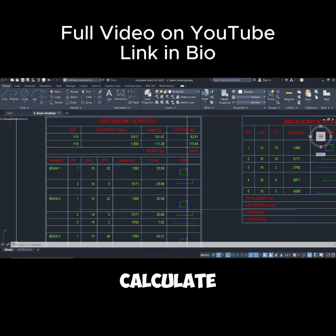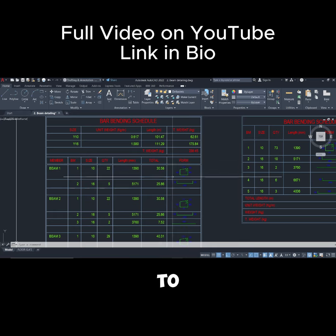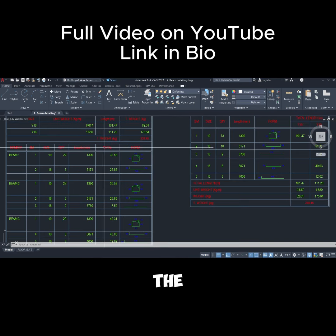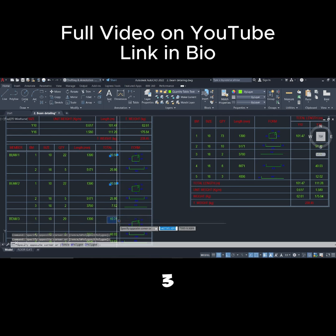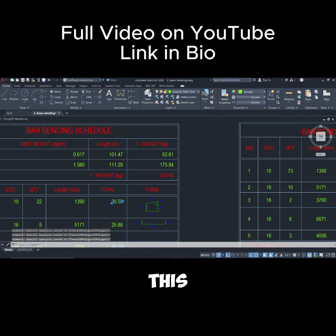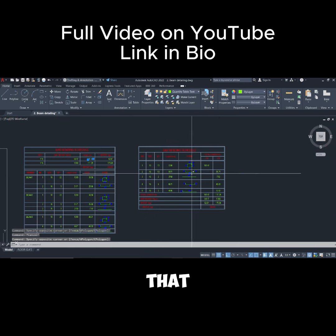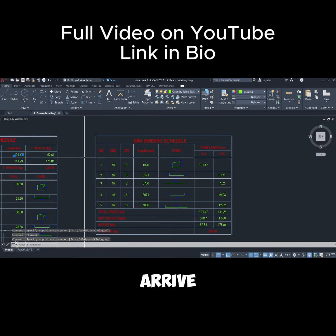But we need to also calculate the total number so that the QS can just come to your bar bending schedule and read the total number of 10 mm reinforcement, total number of 16 mm reinforcement. To calculate the total number of 10 mm, we need to add up 10 mm in beam 1, 10 mm in beam 2, 10 mm in beam 3. So addition of all of this will give us this total length here, 101.47. You can see that it is the same. So we are going to arrive at the same thing.